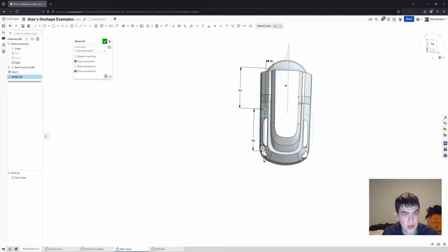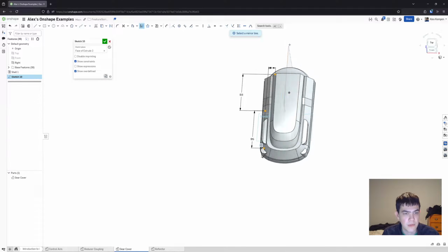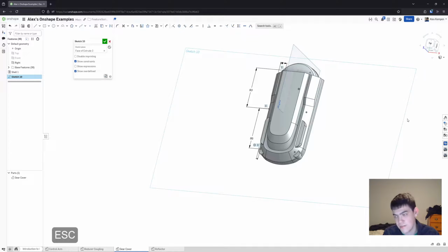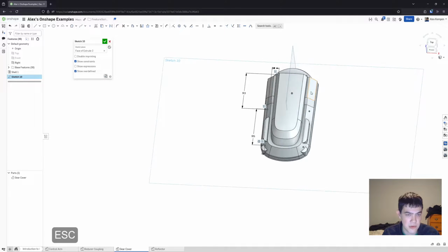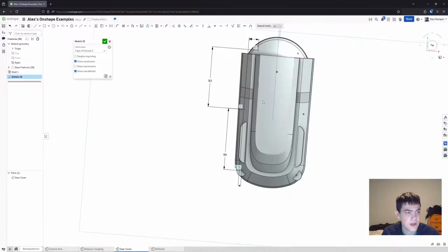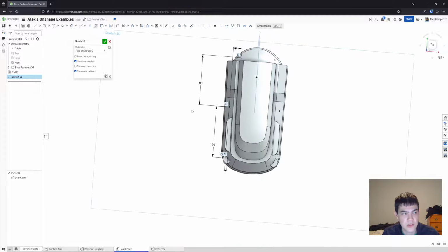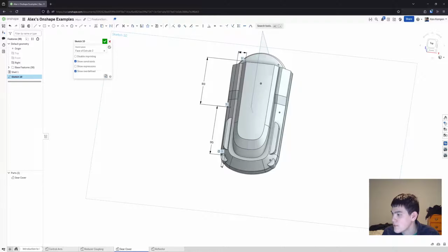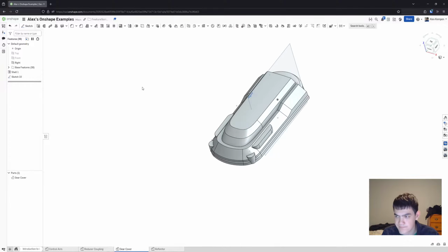And then we want to put these points on the other side, so we'll go ahead and select them, grab mirror, and then we can just mirror about the right plane. They show drawing on a construction line using that, which is also perfectly fine. But I say, if you don't need a construction line, why add one, right? When we can just use a plane. But yeah, so that works. So we'll go ahead and confirm that.